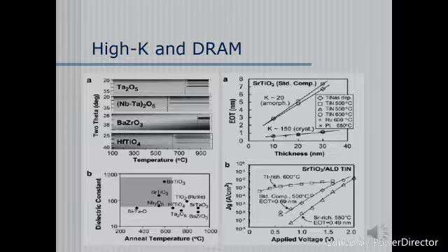This leads to an amorphous SrTiO3. Films with an anneal of 550 degrees Celsius and higher became crystallized into a structure with a dielectric constant of approximately 150. When compared to EOT versus thickness plots, the values of the dielectric constant correspond to the slope of the graph.